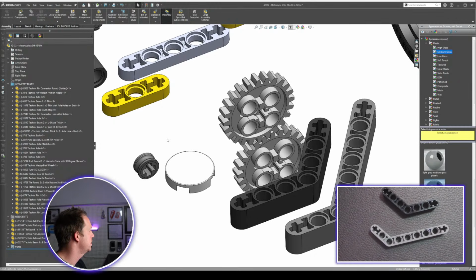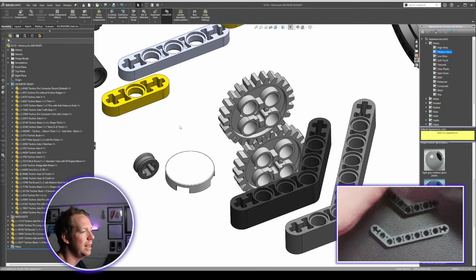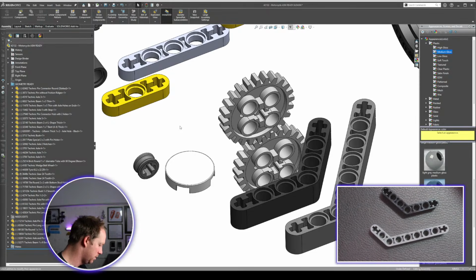Monty, question: how much is recommended to get proper slide fit of plastic parts? Great question. It depends on a lot of factors. Depends on how big your job is. So are you dealing with something in millimeters or centimeters or bigger? At this scale, if they're injection molded, you probably want 0.2 of a millimeter.